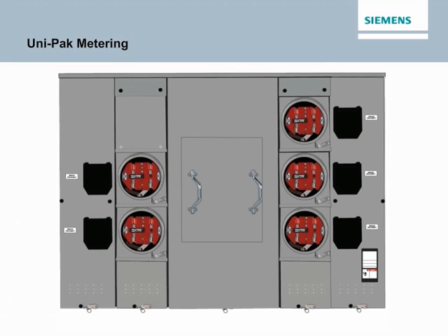A Unipack configuration always consists of a utility pole section with main lugs or stud terminations, 2 to 6 125 amp meter sockets, up to 65,000 amp interrupting rating, or 200 amp meter sockets, up to 100,000 amp interrupting rating, tenant circuit breaker provisions, and a floating dead front. Both ring and ringless meter covers are available. Because this design limits the number of meter compartments to 6, a main switch or circuit breaker is not required to comply with the National Electrical Code 6 disconnect rule.